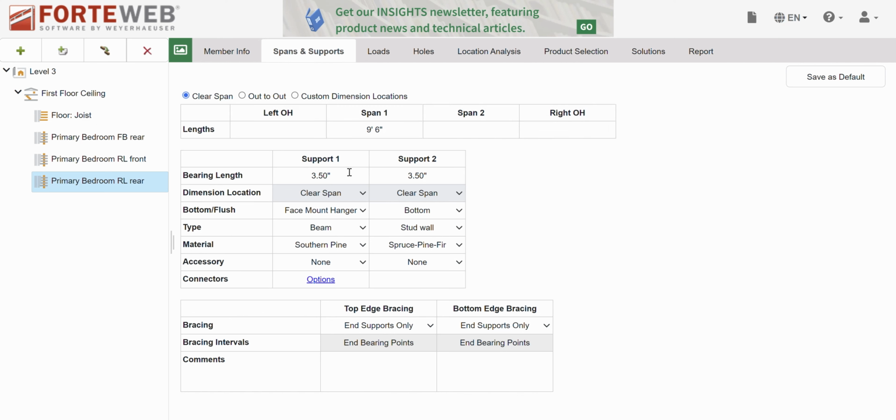9.5 feet, and we are on wall to wall. So it's sitting on the bottom of a stud wall. Well, its bottom is sitting on a stud wall. And there's probably blocking on it, but that's not going to make a huge difference. Okay, what loads are we dealing with here? Okay, ceiling is running left to right. Not a problem. Roof is running left to right. Not a problem. Why is this here? It's here to catch this beam and define this edge for the dormer. So we're going to deal with maybe a little bit extra ceiling weight. We'll call it like a 2-foot tributary width of ceiling. And then this beam's going to load this spot right here. Well, where is that? 3'1". We'll call it 3 feet in.